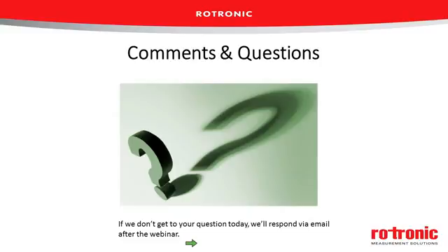There might be other sources of humidity or temperature affecting the reading, and that can be as simple as a user standing right over the instrument, breathing nearby, and your breath, of course, has a lot of water vapor in it, and that can be affecting your readings. So I think there could be a lot of other things to keep in mind here, just in where that instrument is coming from, beyond just the absolute response time of the sensor itself.